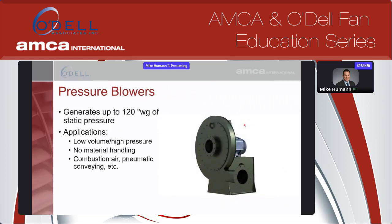Another style of radial wheel is a pressure blower. These wheels are a lot narrower than the normal style paddle wheel. These wheels generate high pressures and low volumes. So they're very narrow. You can see that there's a very small inlet and a small outlet, and that is to help with pressure generation. We don't handle as much air in these, so they're not designed for that.